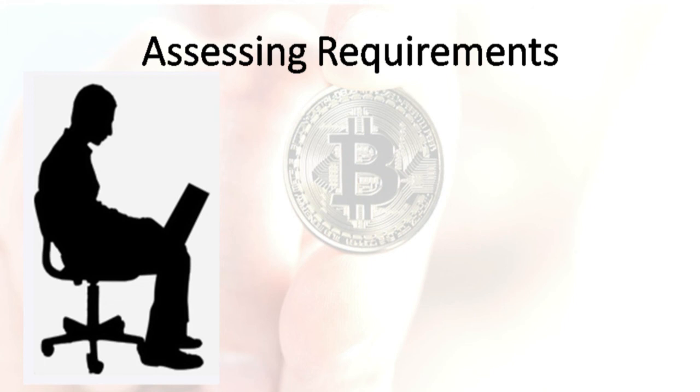You will need to consider how much power the overall facility can consume, whether you are constructing your own mining facility or just leasing a co-location space. In such a case, you can create a spreadsheet and plug in a nameplate maximum power for each component that will be in your mining facility and just sum them up. If you don't trust the specs of the nameplate to be realistic in your situation, and let's be honest, in most cases it won't, you can take real measurements with power meters of the component and multiply by the quantity that you will deploy.